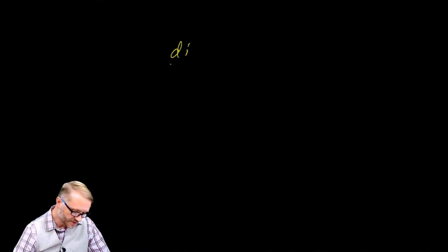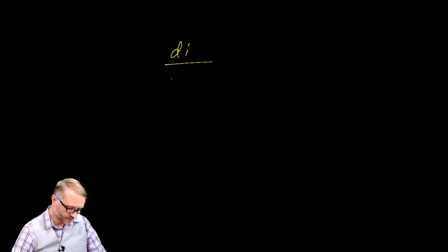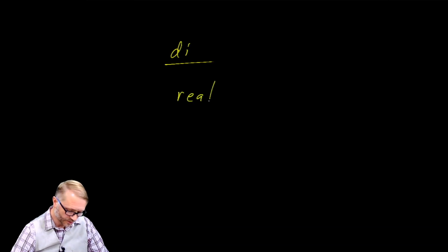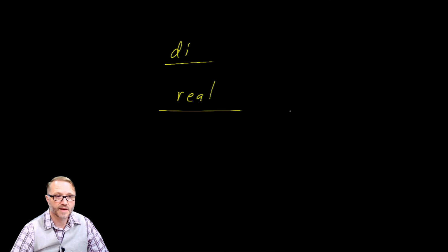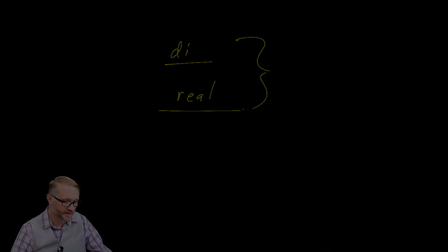Because every time you use a very large variable like a double integer, it puts an extra load on the PLC and can slow things down, and in extreme cases can actually consume memory that you might need for something else. Some folks will just make everything a type real, which has the same problem, you end up having a memory and performance penalty. And for some applications, it just doesn't make any difference. For others, it can be a problem. So you'll have to decide that on a case-by-case basis.